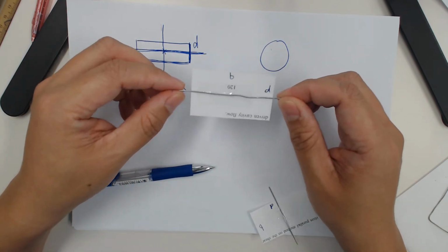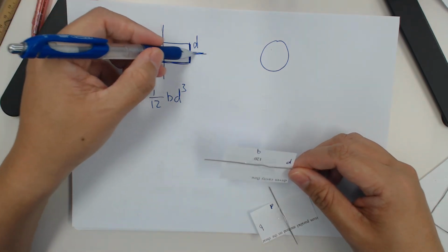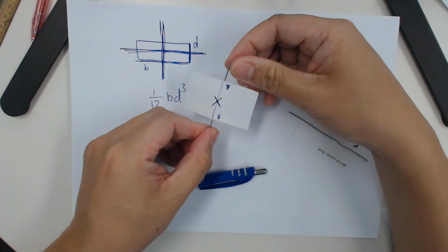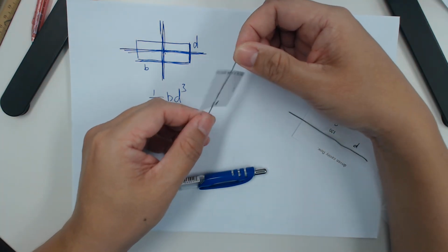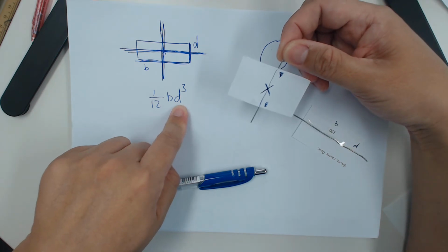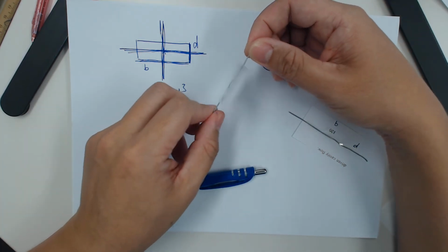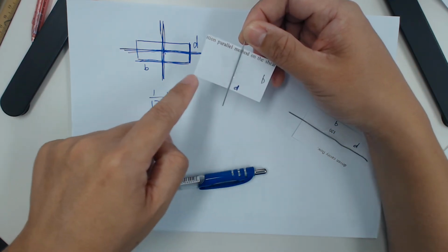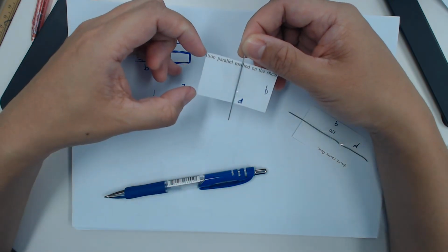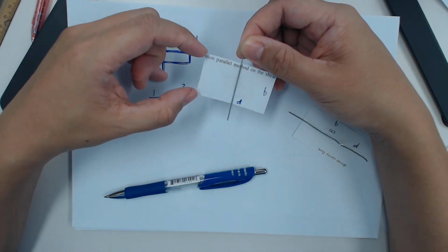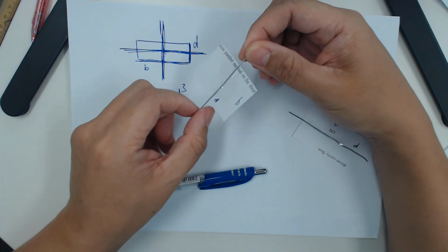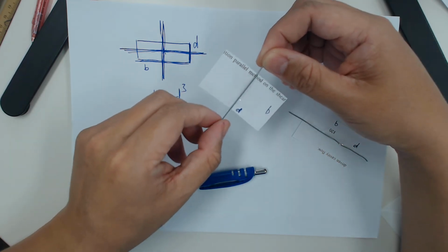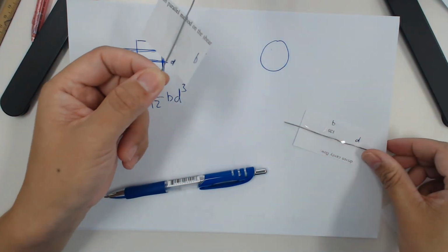If I now look at the vertical axis instead of this horizontal axis, so this would be the case. You're doing this now. So the D is always the side that is perpendicular to the axis. So for this case, this long side will be D, and the short side will be B. So this is how you remember: you cube the side which is perpendicular to the axis. So this is the kind of illustration.